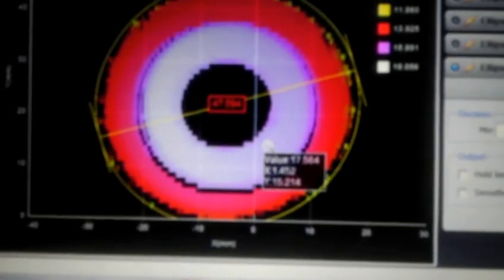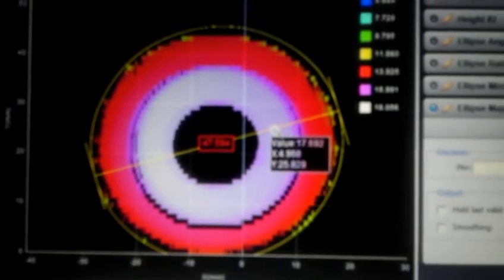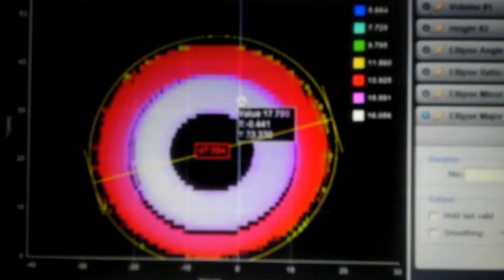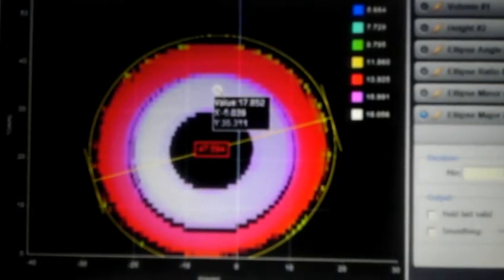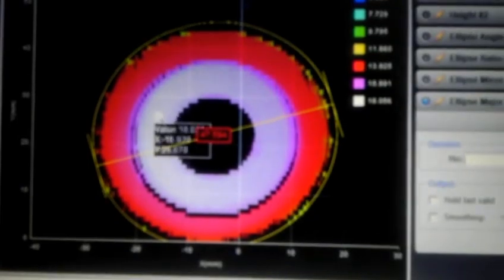So I can really see the idea of this bushing, and I can see that 18 millimeters is what I'm roughly getting with this shade here. If I move my mouse around, I can actually see that it's more like 16, 14 millimeters anywhere on the surface here. So it is varying a little bit. Probably hard for you to see, but I can see different values of it. 17.8. So I can tell if that bushing is pushed all the way down or not based on these values.